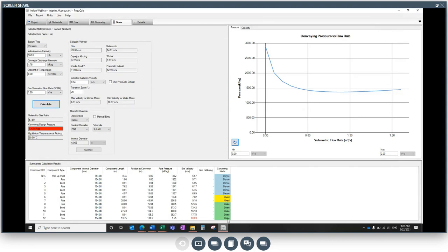So the first thing that I'm going to do is increase the pipe diameter of our system. 300 tons per hour as our instantaneous capacity in a 150 millimeter pipe over this length is requiring too much pressure, and this is something that you'll get familiar with, those numbers, as you use the software.